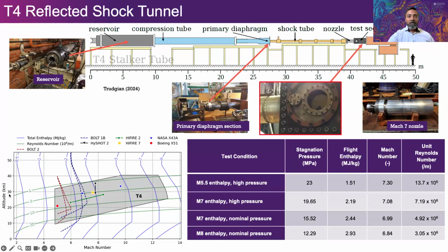And then what is the Reynolds number, which is a fluid mechanic quantity of interest to all regimes, particularly if you want to understand how transition happens and where the flow is turbulent in the vehicle. Now, on top of that, I've also put on some past hypersonic flight experiments just to contextualize and show that this facility, with what it produces in terms of test conditions, adequately captures most of the trajectories or test conditions of past hypersonic flight vehicles. So therefore, it's a ground test facility that produces flight-matched test conditions, and some of those conditions are shown here in a table, as you can see.